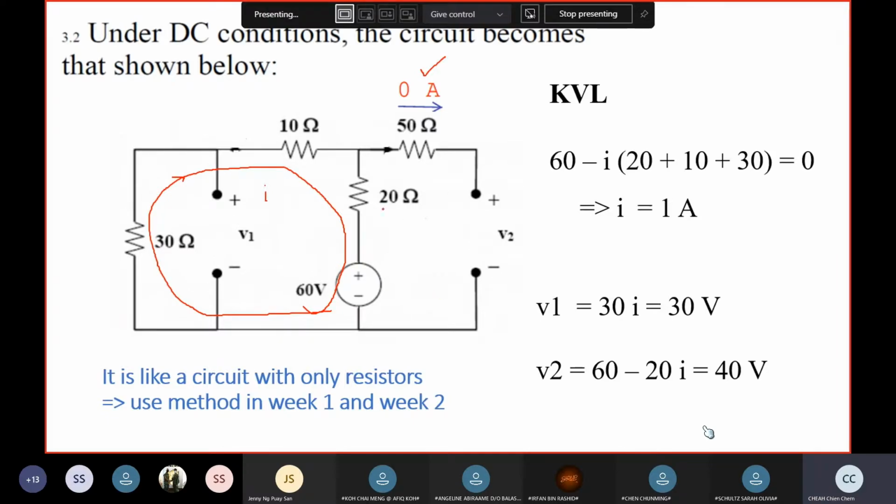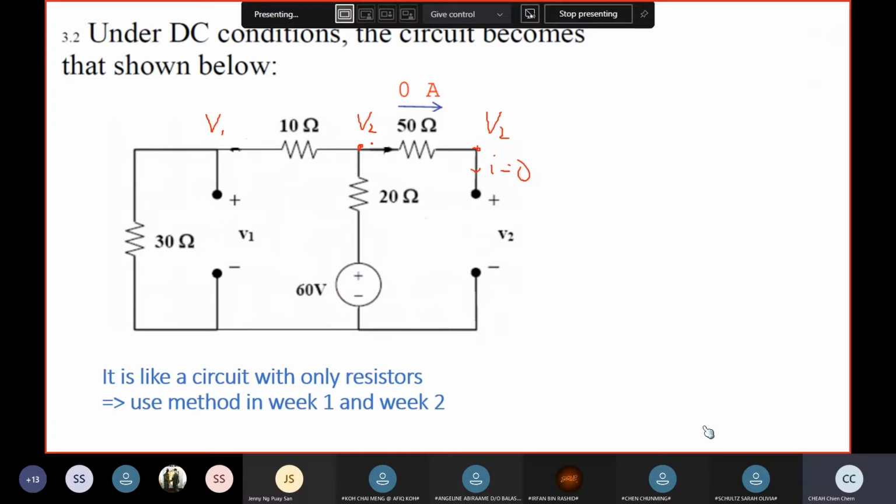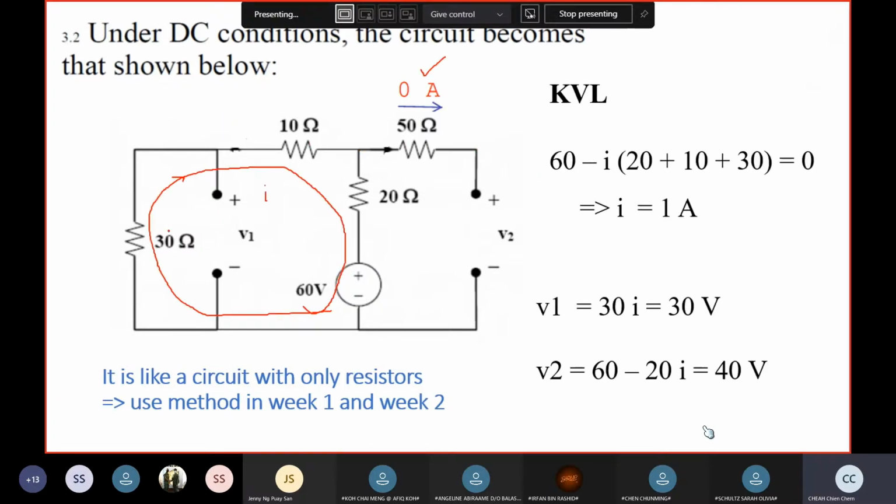So this one only has one equation. You apply mesh analysis, go one round, and you can write down these equations. There's only one unknown, I. Solve for it directly, it is 1 ampere. Of course, mesh analysis means find current, nodal analysis finds voltage. In the end, you still have to find V1 and V2. But once you have a current, then current is related to voltage, correct?